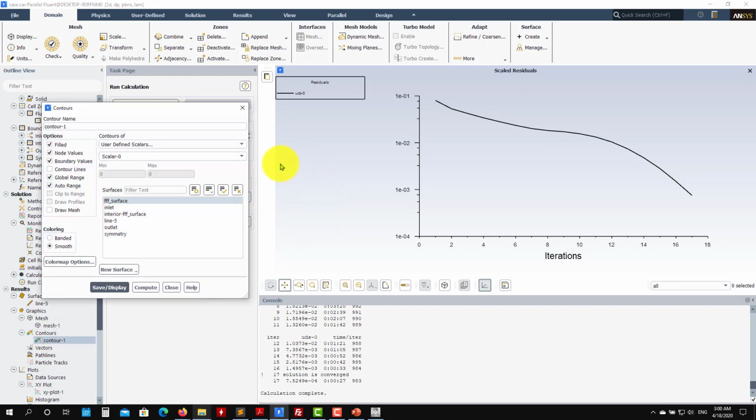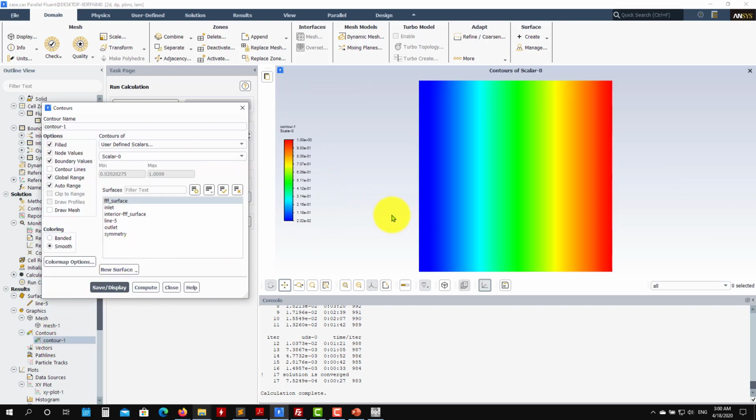This is how to play around with our under-relaxation. So in the next tutorial, we'll prepare another pipe, a little bit different from what we have done so far, but we're going to play with steady and unsteady, and you will see the influence of the relaxation better. For now, I hope you get a good idea of where those numbers are. Bye.